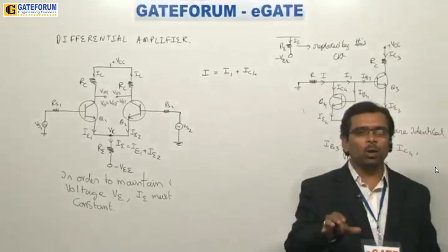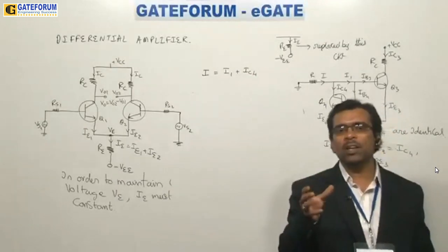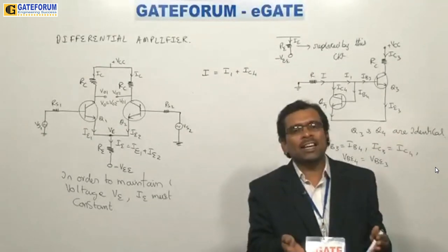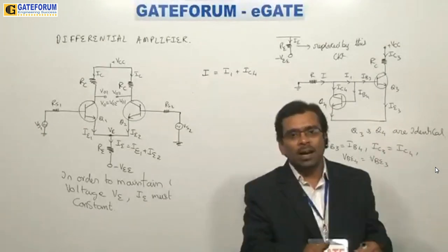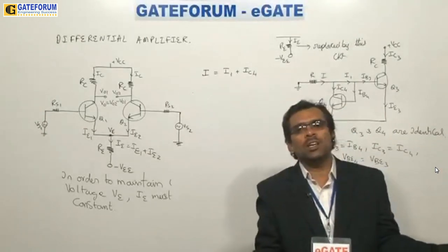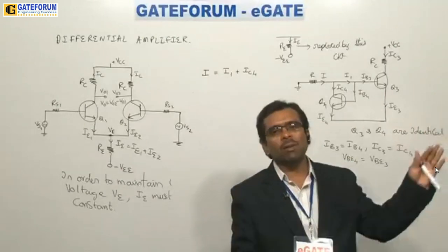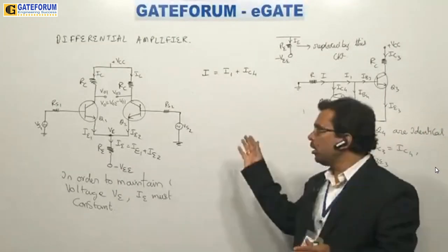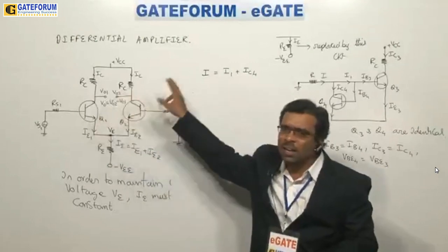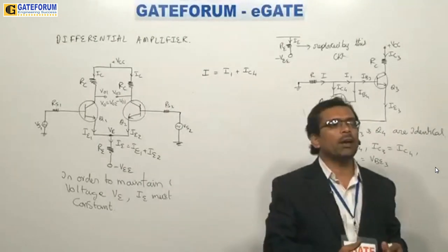And this output what you are giving will not be the final output. It will go as input to the differential amplifier of the next stage. Then you are providing very, very high voltages to the base of the next stage. When you give that much high base voltage, immediately the next stage transistors will go to saturation. They will not be in cutoff either, they will go to saturation. When they go into saturation, the output voltage is nothing but plus VCC or minus VSAT, minus VCC. So quickly the transistor will go from the linear region to a non-linear region. You are looking at only this circuit on the board, but this output will be connected to the input of the next stage. As this output is a high voltage variation, if you give it to the next transistor, the base will become more, and the transistor will go to the cutoff region. So it is very difficult to manage.